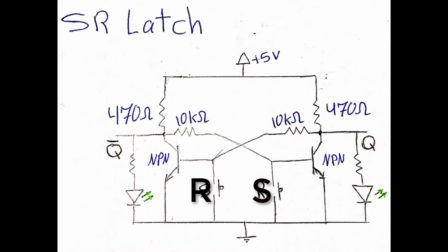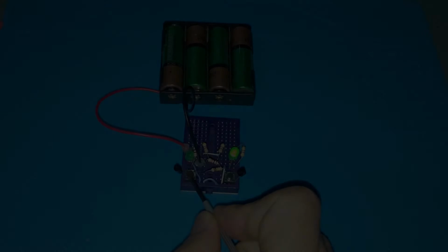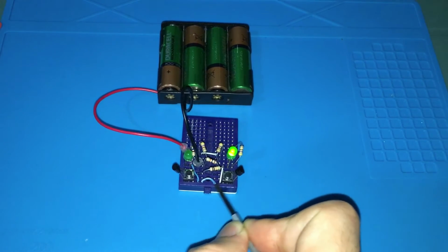As a final note, I noticed that many people on the internet consider this circuit a flip-flop, but it's not, because a flip-flop has a clock input feeding it, while a latch circuit doesn't. Alright, we are done with the theory now. So for the sake of demonstration, let's build up this circuit on a breadboard and see how it will perform.